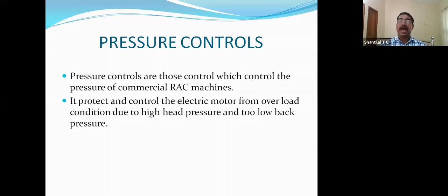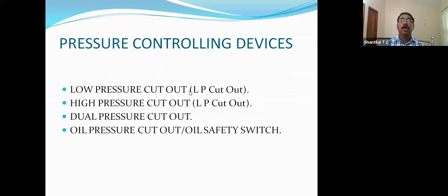Overload conditions mean too high head pressure or too low back pressure. Back pressure means suction pressure. The pressure controlling devices are: low pressure cutout, simply called LP cutout, high pressure cutout, HP cutout, dual pressure cutout, and oil pressure cutout or oil safety switch. Oil pressure cutout is sometimes called an oil safety switch.